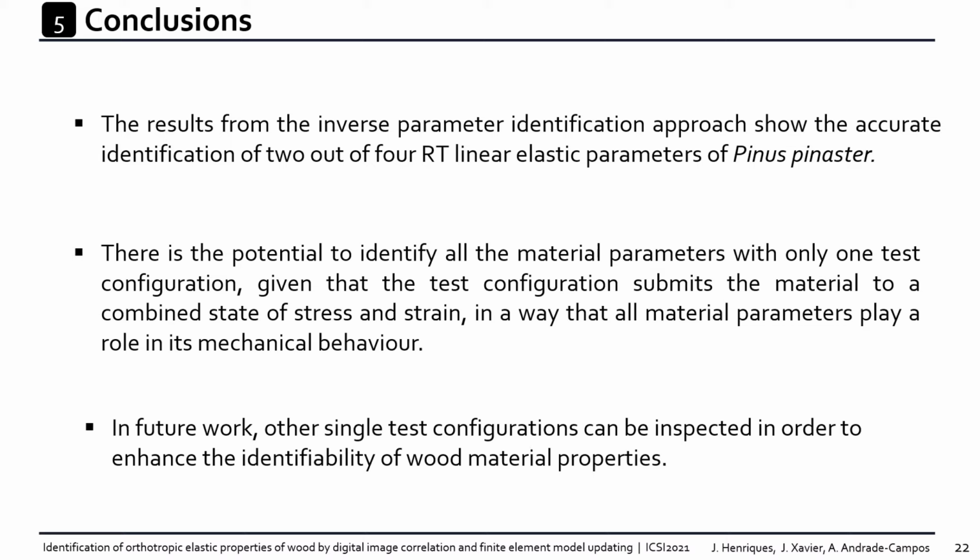Nevertheless, there is the potential to identify all material parameters with only one test configuration, given that the test configuration submits the material to a combined state of stress and strain in a way that all material parameters play a role in its mechanical behavior. In future work, other single test configurations can be inspected in order to enhance the identifiability of material properties.